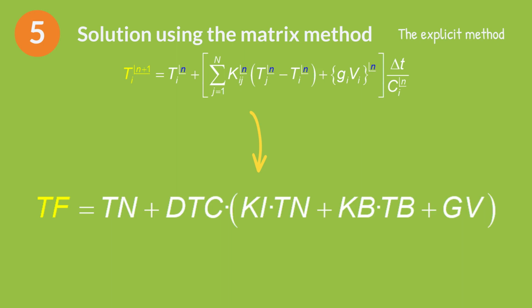It can be seen how the temperature in node i depends on the neighboring nodes, the bordering nodes, and its own internal heat generation. For the same amount of energy input, the temperature of the node will evolve in the transient state faster or slower, depending on its heat capacity C.